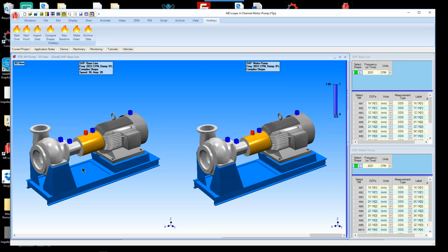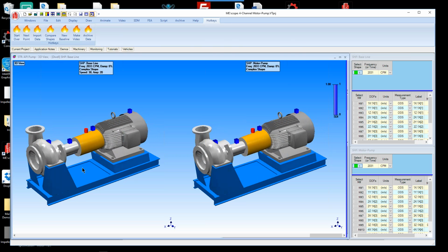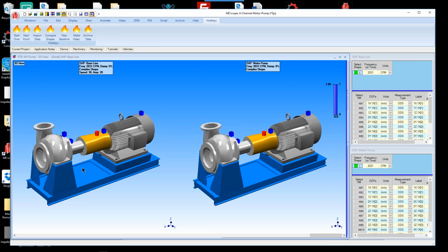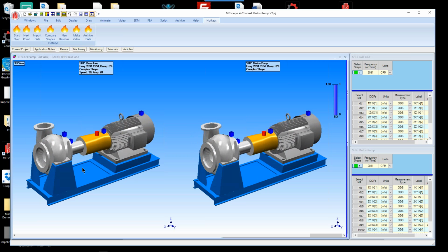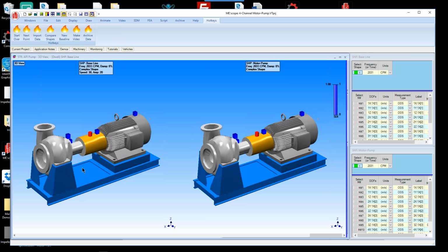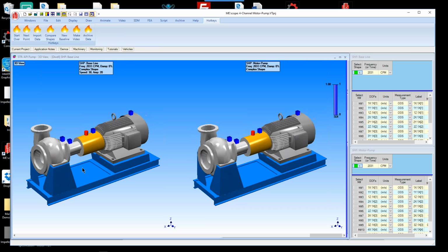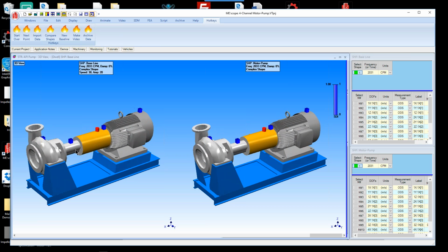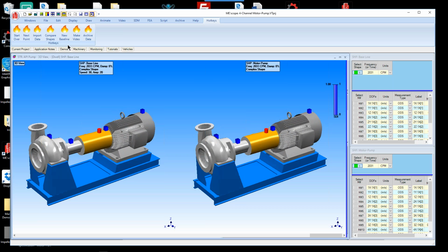After we look at this, then we'll look at how we can do the same thing with a two-channel analyzer, where we would just use two uniaxial accelerometers. One's our reference, it doesn't move, and the other is roving, moving to each of the positions where we want to measure the ODS. So let me go ahead and make a movie here, and this is kind of the end of the story, and then we'll go back to the beginning.